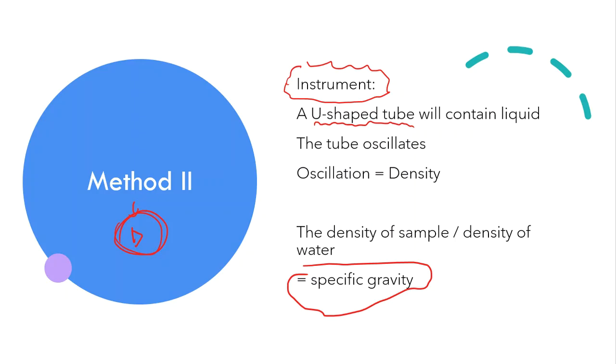The instrument is measuring the density of the sample. It knows the density of water at the temperature you're making the measurement at, and it takes those two densities and divides them. That's how it's calculating the specific gravity for you. So on the report, you will find a straight-up density read. It gives you that because it's going through the motion to do it anyway. Then down at the bottom, or somewhere else on the report, you're going to see a specific gravity number as well. It does give you both. It's got to have that number anyway, so it's going to report that number to you.